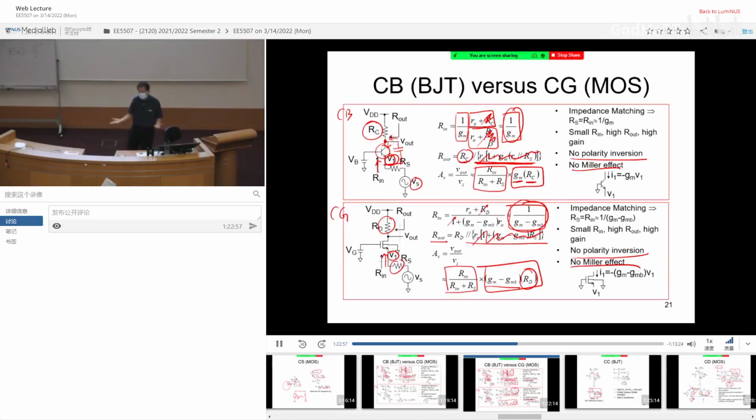Why? Because you are dealing with different kinds of source. When you are dealing with RF, you are absorbing power from the antenna. You are dealing with a power source, so you want to maximize the energy you can extract. Therefore, you need to use maximum power transfer. That is RF.